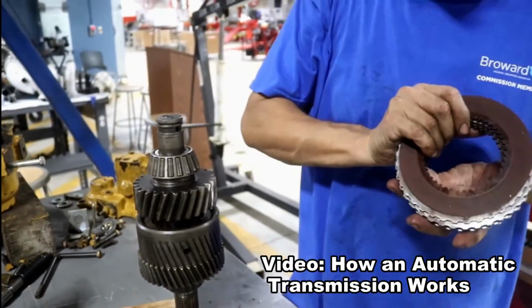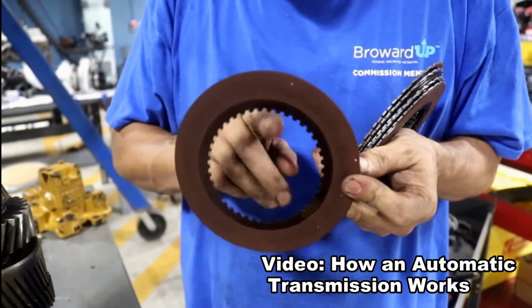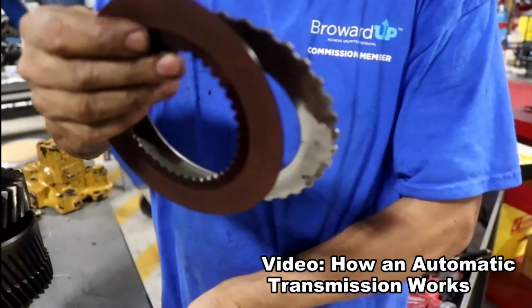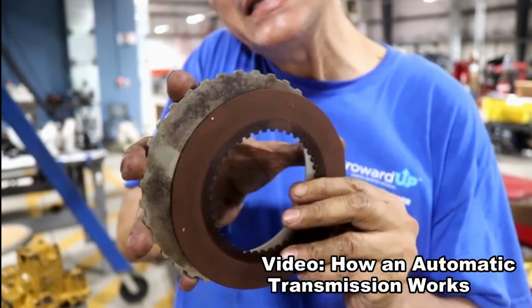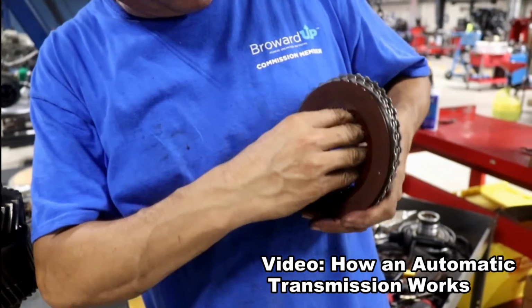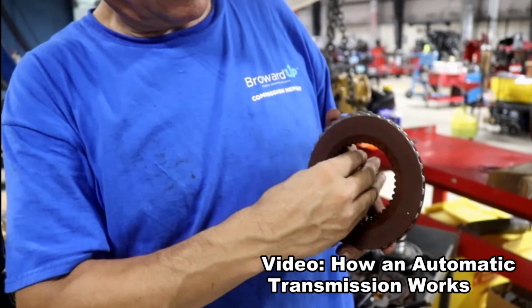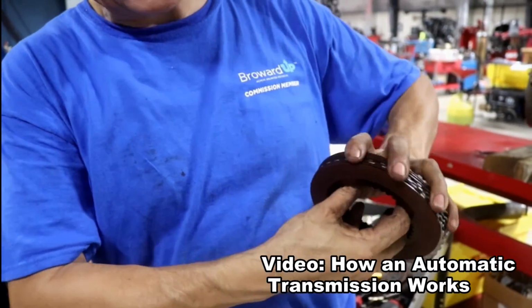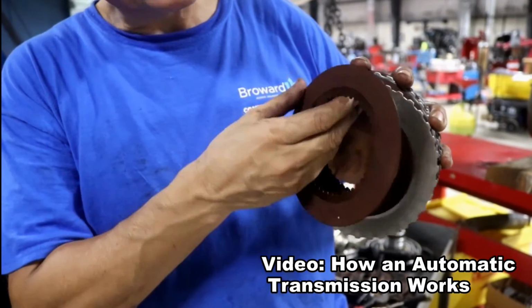If you check those plates, the friction plates have the teeth internal, and the stainless steel plates have the teeth external. In other words, I have one shaft connected internally with the friction discs, and another case connected externally with the stainless steel plates.